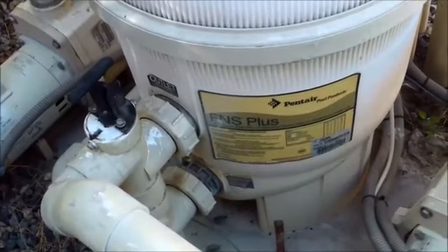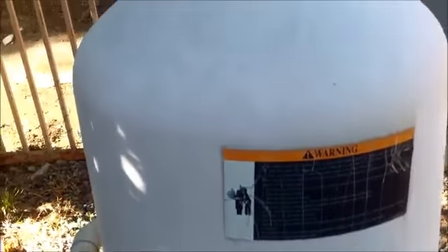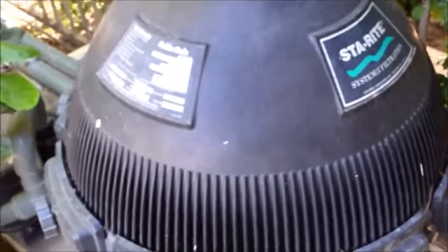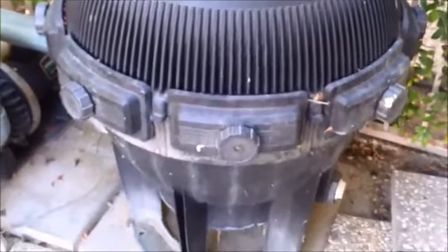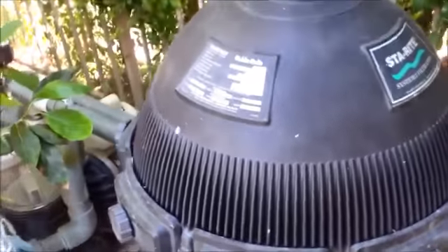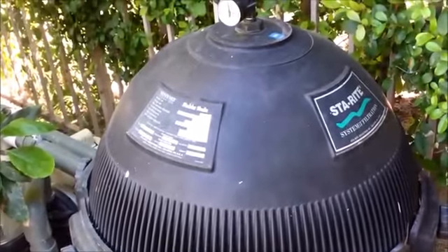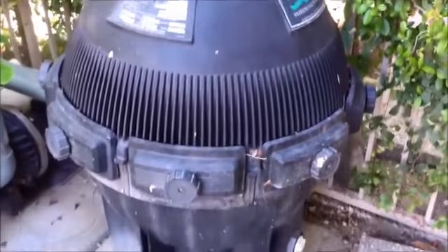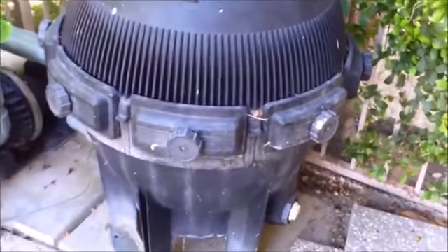You can have various problems with the filter. The DE filter, the elements could leak in there and cause DE to go back in your pool and dirt. You can also have a problem with the backwash valve on a DE filter. And here's a cartridge filter. Basically what happens is that the cartridges over time will go bad in the filter. They rarely will rip and leak, but they will go bad and it won't filter as efficiently. You'll notice that your pool's not filtering well, and that's when you have to replace the cartridges in the cartridge filter.